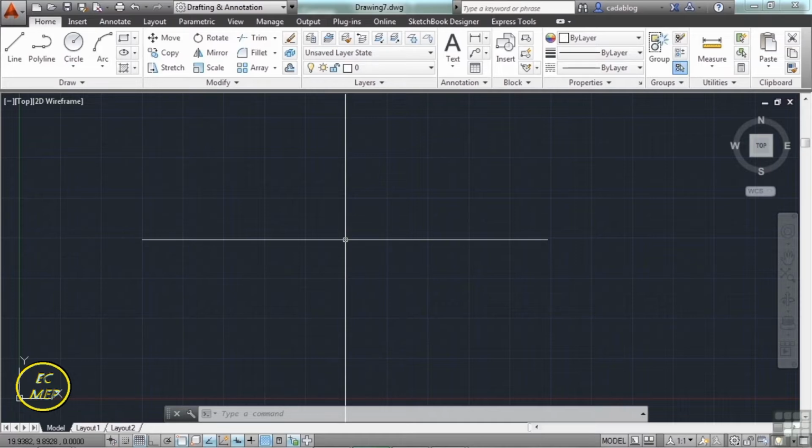Typically, AutoCAD users will work with one set of drawing units, whatever they might be. Sometimes, though, you will need to work with files that are drawn in different units. That's why it's so important to define your units in the Unit Manager. If this is done properly, then AutoCAD can interpret the different units accordingly and scale the line work as needed when you bring it into your drawing. Keep in mind that not all CAD users are created equal, and none of them are as responsible as you are. And they may not have properly set their units. So it's a good idea to check the file before you work with it.